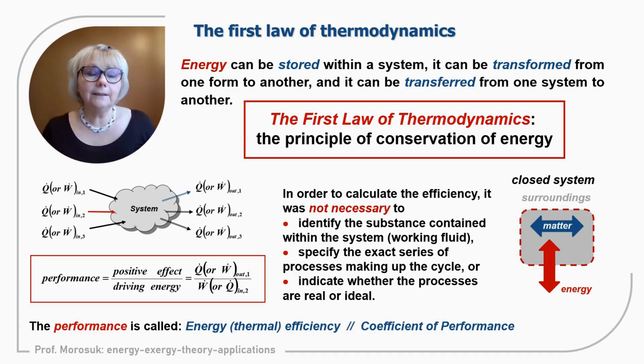And just to repeat, performance or efficiency is called energy efficiency, sometimes thermal efficiency for the direct thermodynamic cycles, and coefficient of performance for inverse thermodynamic cycles, meaning for refrigeration machines or for heat pumps.